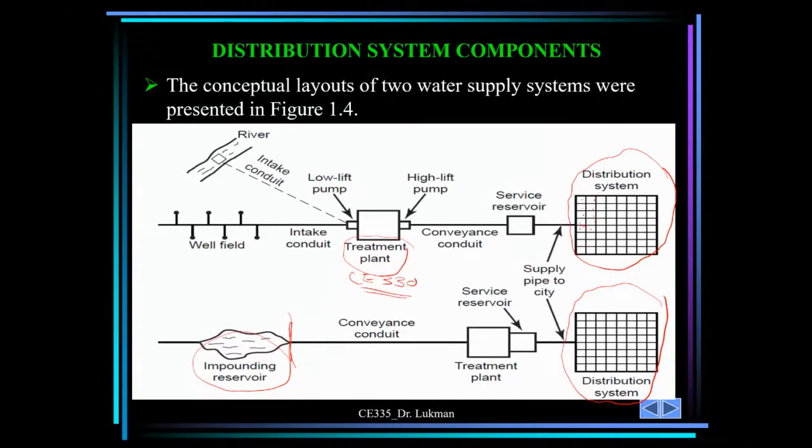That is when the water reaches the treatment plant, what happens: all the unit operations and processes, from coagulation, sedimentation, or even flotation may precede that, depending on the water quality. And then from sedimentation, to filtration, from filtration to disinfection, from disinfection, you now convey it again. You pump it to the service reservoir and then to the distribution system.